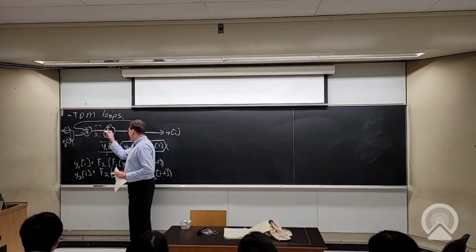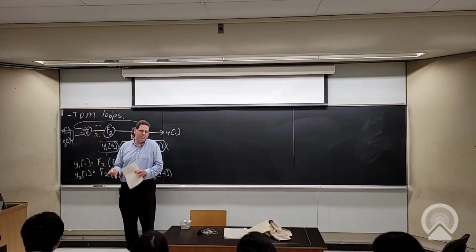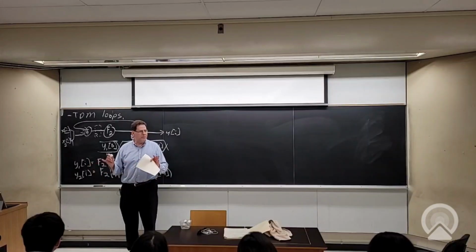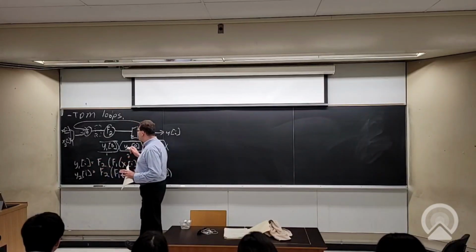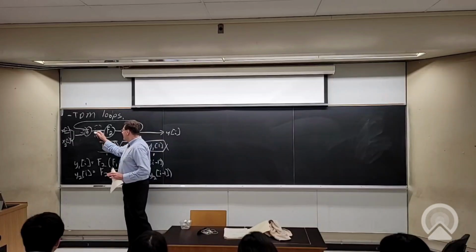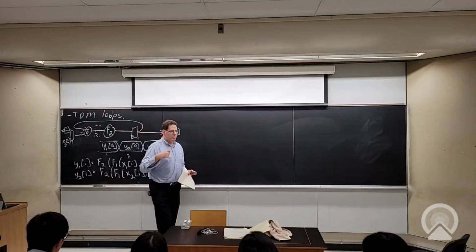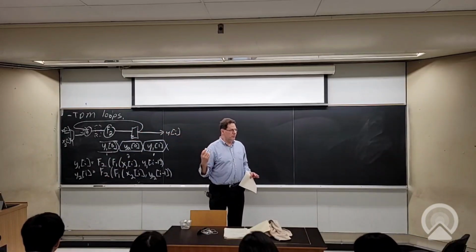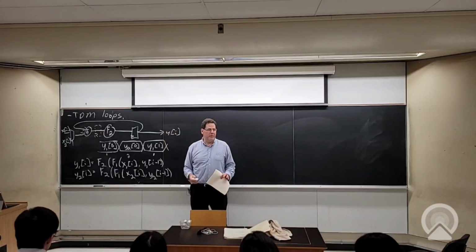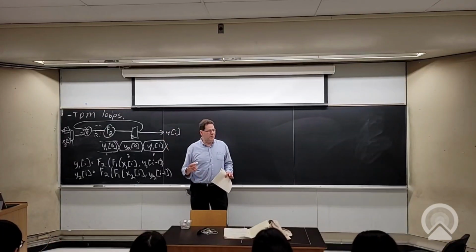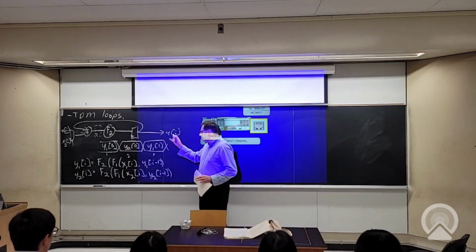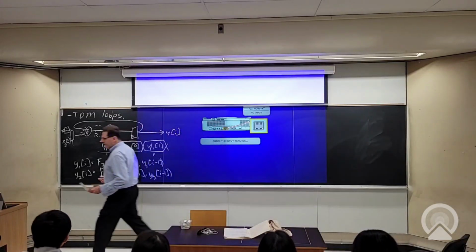Maybe it has 1 cycle of latency, which would be pretty common, or maybe you wrote it with 2 cycles of latency. Whatever it has, if you want to time domain multiplex it, you have to make 2 copies of every register around the loop, and then time domain multiplex by a factor of 2. Does that make sense? So it works for loops with longer latencies as well.